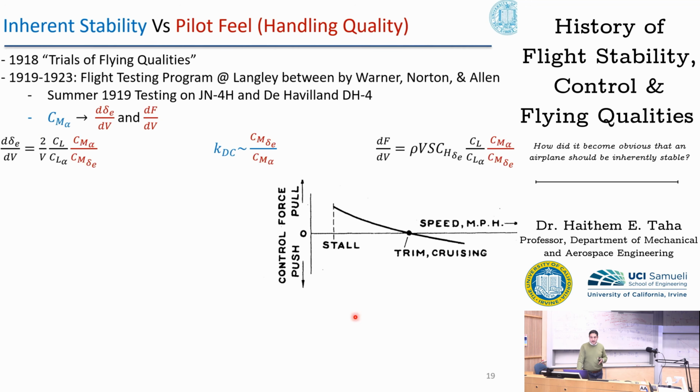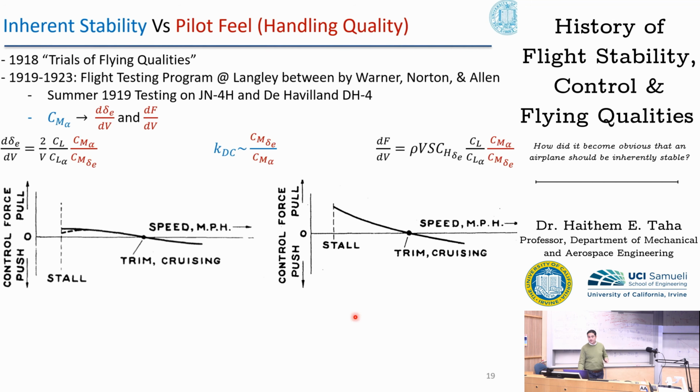So people at the time figured out this criterion to compare the stability of 2 given airplanes from flight measurements by focusing on this stick force curve. As you can see, here we have a considerable slope implying considerable stability. Here we have a weak slope implying weak stability.